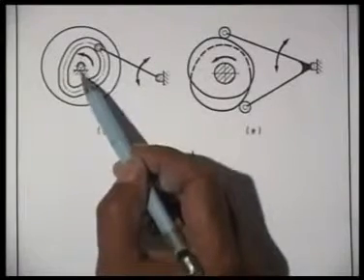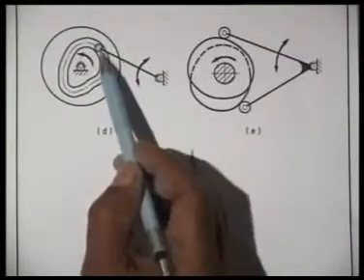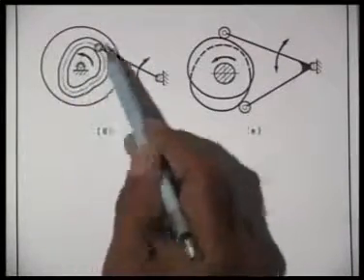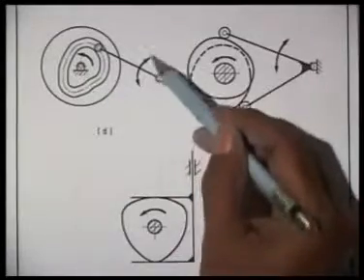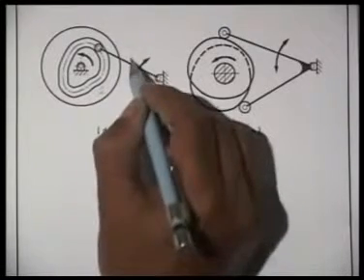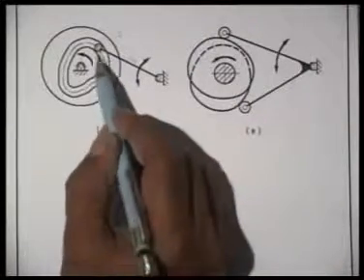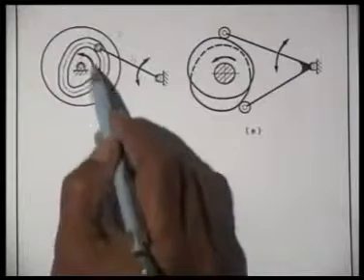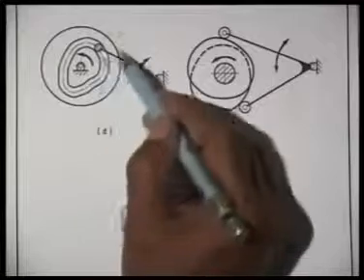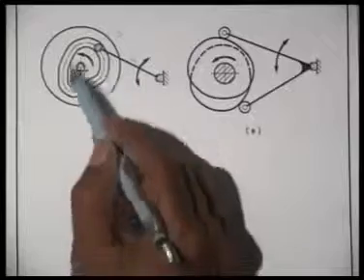In this diagram, as we have shown, no spring is necessary because the roller follower is placed in a groove. The shape of the groove is nothing but the shape of the cam, which will dictate the type of angular motion that this follower will have. So this is the cam and this is the follower, and this roller 3 has been placed inside a groove in this body 2. So as this body 2 rotates, depending on the nature or the profile of this center line, this roller will be pushed up or brought down, and it will be always within the groove.